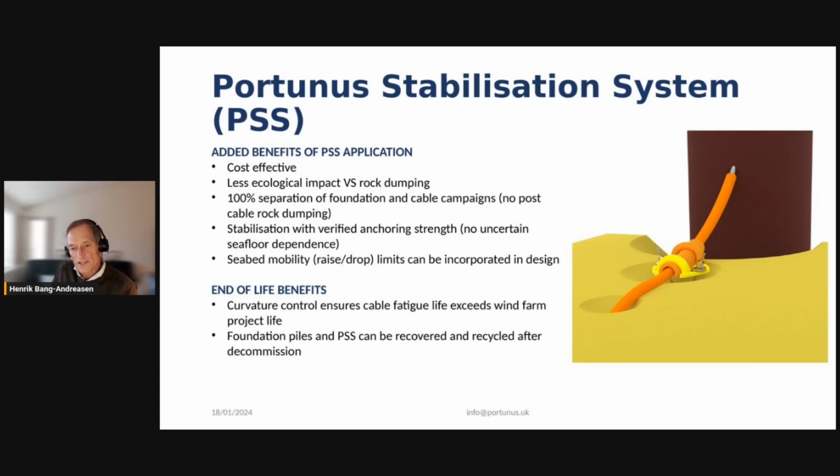And the stabilization obviously comes with the verified anchoring strength. So there's no uncertainty. You don't have any dependence on what kind of strength you actually achieve in the seabed, or what kind of seabed you have from the CPT or whatever surveys have been made. You actually get the validated anchoring strength from the screw pile operation.